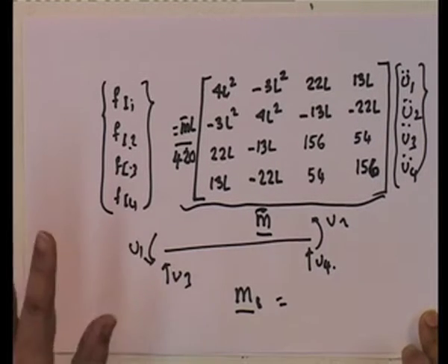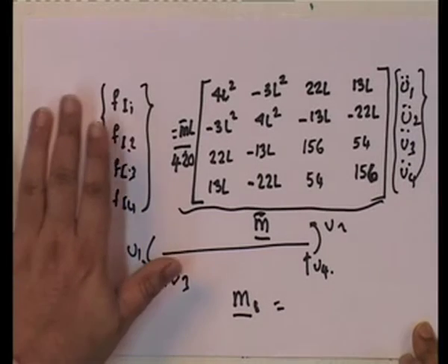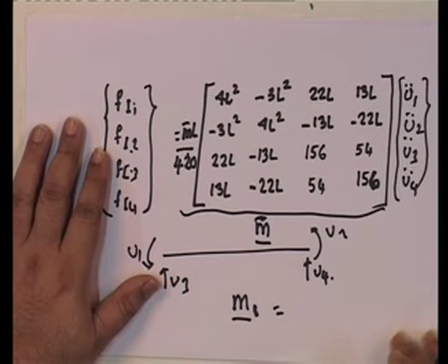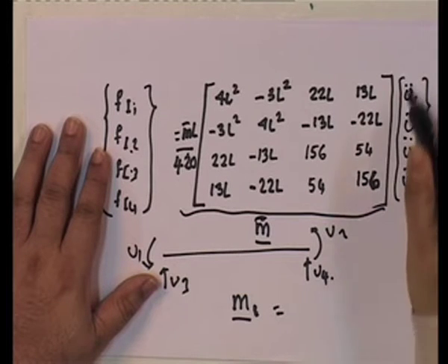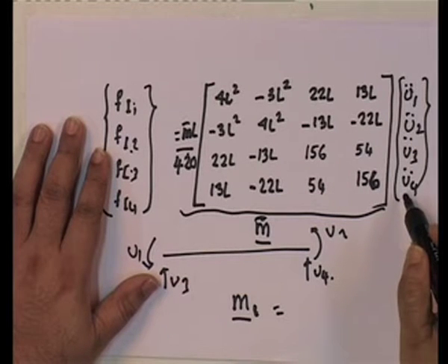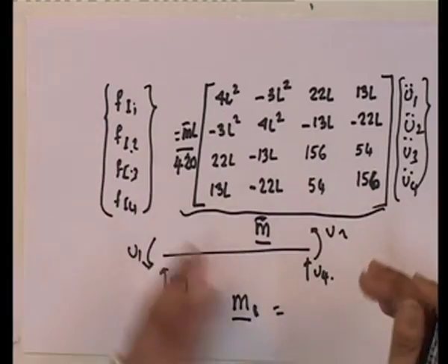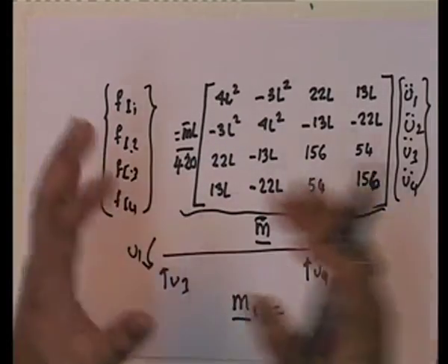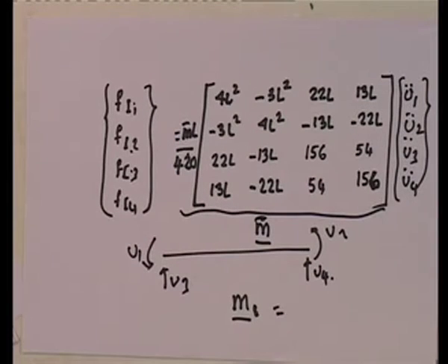And once you have this, this is the inertial force. Now, all you have to do is find out the end accelerations, and you can do it exactly the way you get the structure stiffness matrix. You can get the mass matrix corresponding to this, and then you have got your K and mass for a given structure.